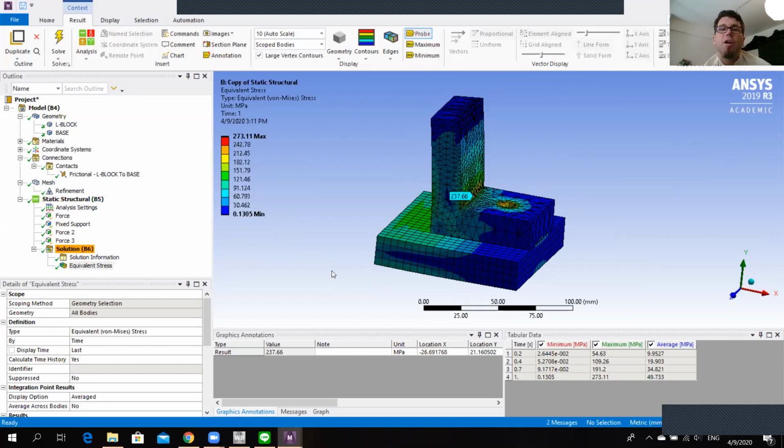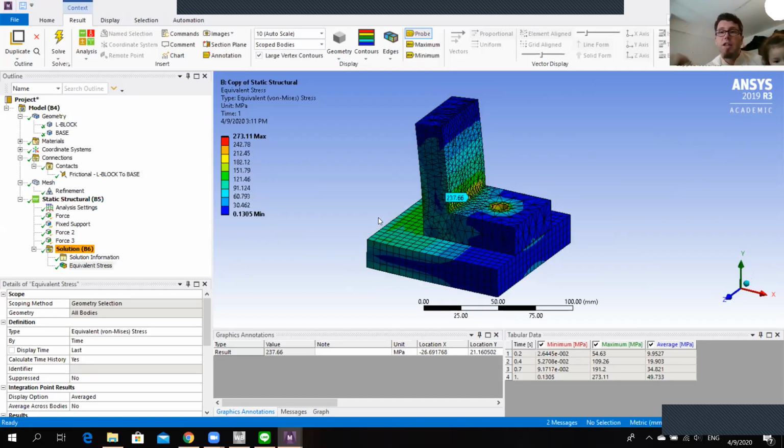And the bending part on the aluminium is, well, it varies. Near the corner, it's getting into the same region. So we have a similar stress level. If you have high strength aluminium, that would give you maybe a yield strength of around 200 megapascal. Regular steel has a similar yield stress. So I would say if this was my structural design for something, I would be pleased with the general design. I would not be pleased with the stress concentration in the corner. So I would want to change the detailed design of that aluminium part, so we don't have a high stress concentration in the corner.